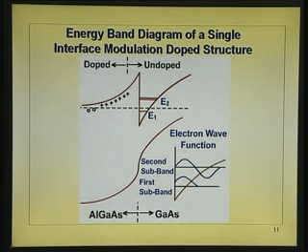You will see here there is a doped layer up to this point, that is aluminum gallium arsenide. There is a small undoped layer here, aluminum gallium arsenide, same band gap, but the dopants are not there. This shows the dopants are stopped there, and beyond this point is undoped gallium arsenide. You get of course the notch here, and how deep this notch is depends upon the mole fraction of aluminum gallium arsenide. So, the thin layer you put it here.